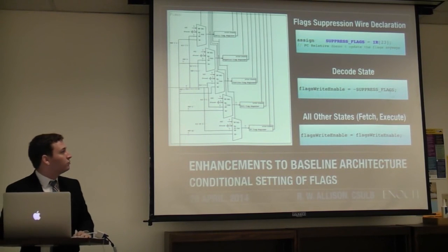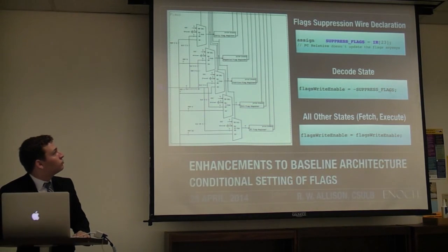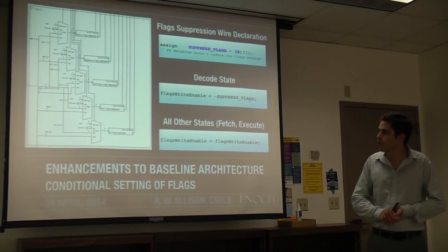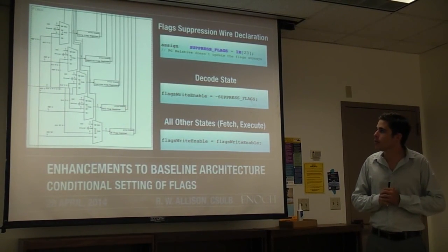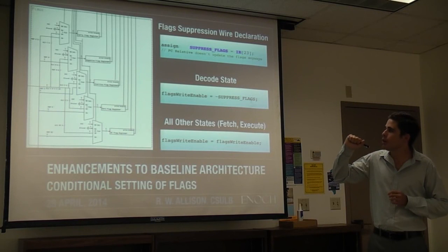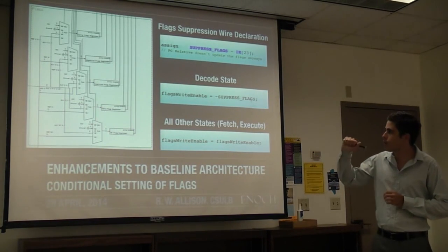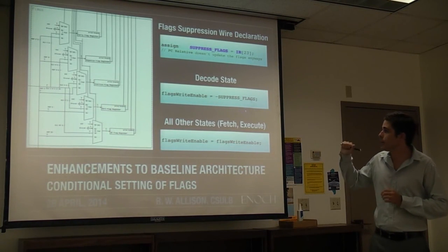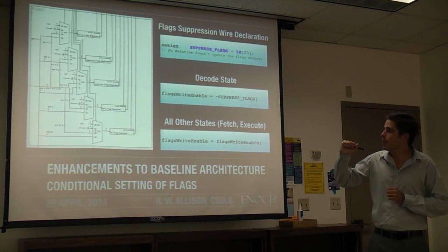To go over our hardware a little bit, this is the wire I was talking about coming out of our IDP. It is a 5-bit wire which has the carry, negative, 0, overflow, and interrupt enable bits. And what they do is they feed into 5 separate muxes along with 5 1-bit registers that have the write enable signal right here. And what that's able to do is when we have the S bit, if we pick write enable, when that's low, they're not going to write anyway.